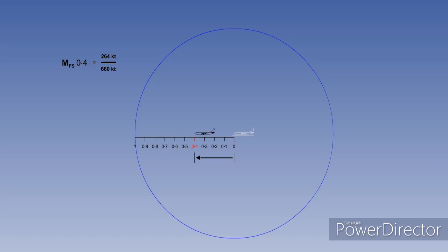But this fact doesn't help us understand how high-speed flight affects the aircraft. It is this that will have an effect on the aircraft: how close the aircraft is to the leading pressure wave. We can now examine how the pressure wave changes the airflow approaching the aircraft. As soon as the pressure wave passes over an air particle, it is no longer relative airflow. It becomes effective airflow. The leading pressure wave effectively acts as a messenger. It tells the air, "Here comes an aeroplane, you'd better get out of the way."